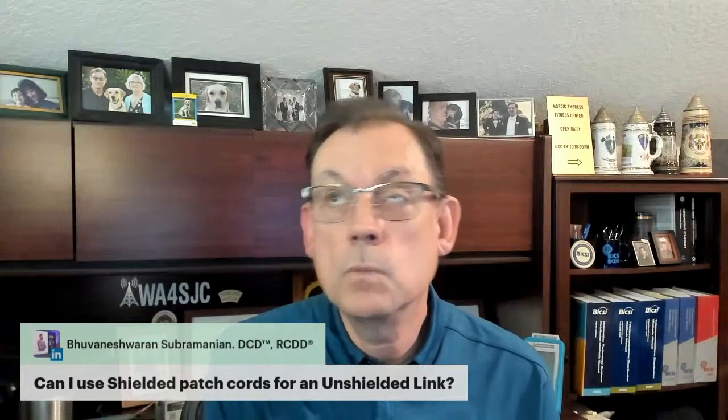Somebody said, can I use shielded patch cords for an unshielded link? Yes, you can use shielded patch cords for an unshielded link. Technically, you probably want to keep the same all the way through, but you could use shielded patch cords. Now, here's something to keep in mind. Your equipment is shielded and it's grounded. So when you're plugging into equipment, you're plugging a shielded patch cord into that equipment.